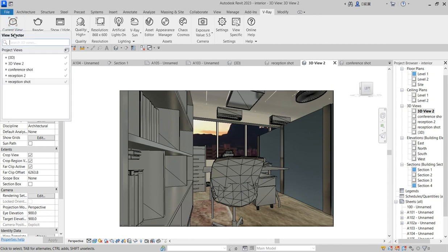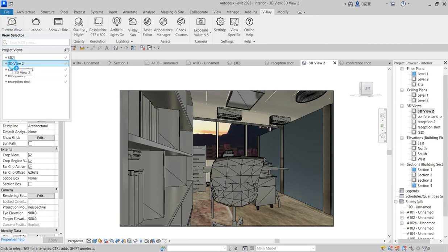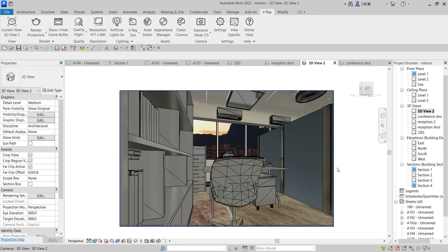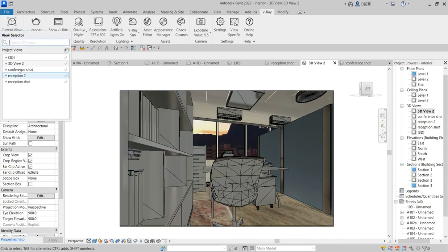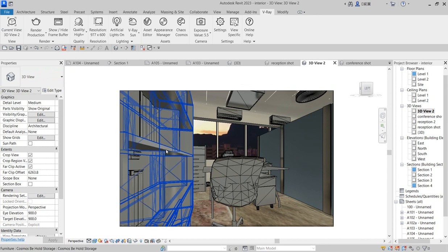And how do you do it? You click here and you change the camera of what you are choosing in the rendering, because if you do not choose a particular camera, it's going to render whatever is available. So in that aspect, you set every other one. Render production, still leave it for now.